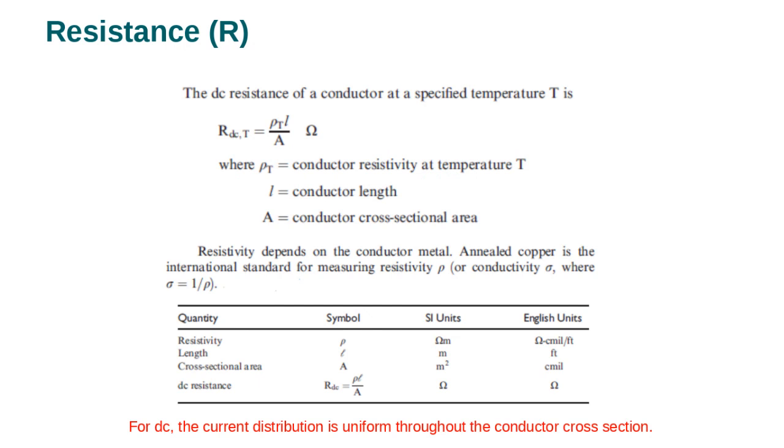And then we also talked about the resistance and how to calculate it. If you increase the length, the resistance will increase. If you increase the cross-sectional area, the resistance will decrease. I related it to the simple wiring system in your house, for example. If you are connecting an oven in the kitchen, this will have about 6 millimeter wire.